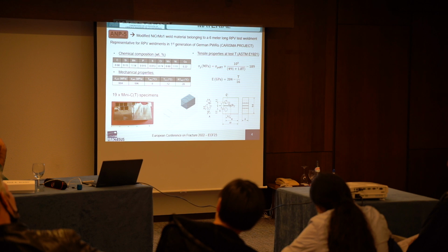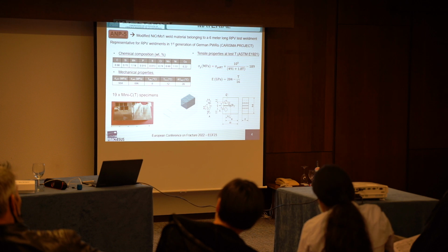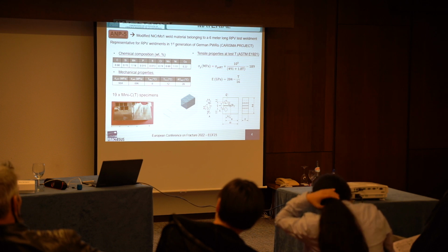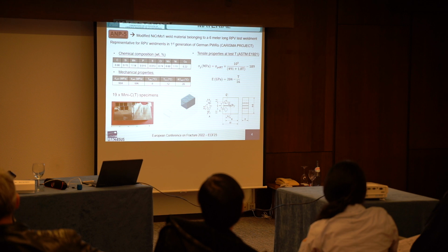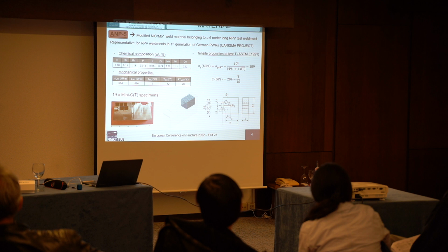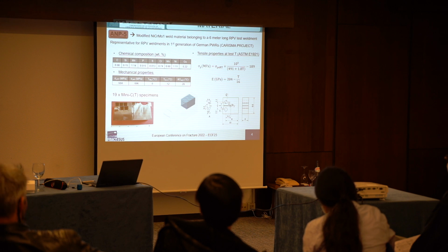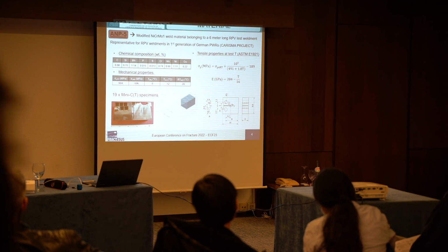Yeah, but that's why we check the fractography. We check to see if we encounter multiple site initiations or just only one. And in this case, we have only one initiation area. That's why I say that we can fit the weakest link theory. Because if not, you would encounter multiple sites of crack initiation, you know?